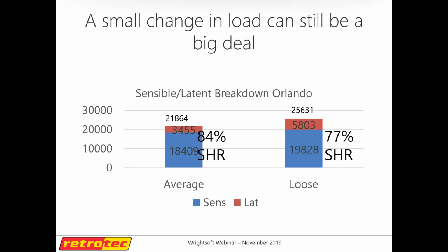The problem with that is the relationship of the temperatures of things to dew point. And when you design something to be more efficient, if you don't increase the cost somehow, if you don't start to get clever in the way you design it, it just gets less and less good at removing moisture, right? And so there's pressure on the manufacturers to maintain cost controls, right? They don't want to double the cost of an air conditioner. No one will buy it. But there's also pressure on them to make things more efficient. And so what you get are systems that don't maintain 70% sensible heat ratios.